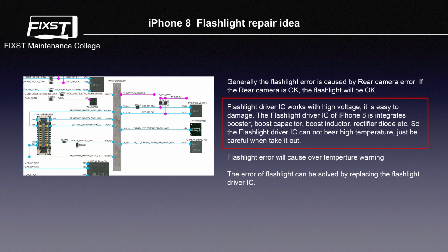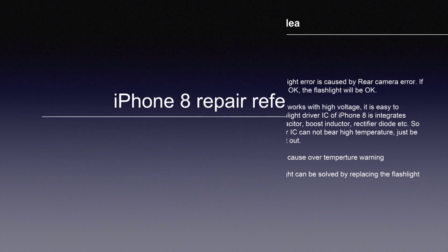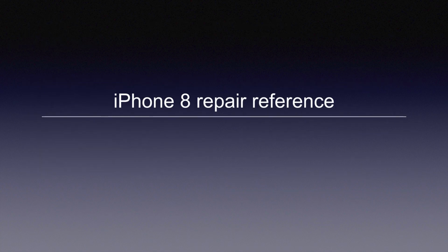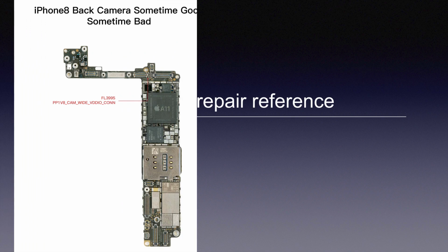So the flashlight driver IC cannot bear high temperature. Just be careful when taking it out. Flashlight error will cause an over temperature warning. The error of the flashlight can be solved by replacing the flashlight driver IC. Next, let's see iPhone 8 repair reference.